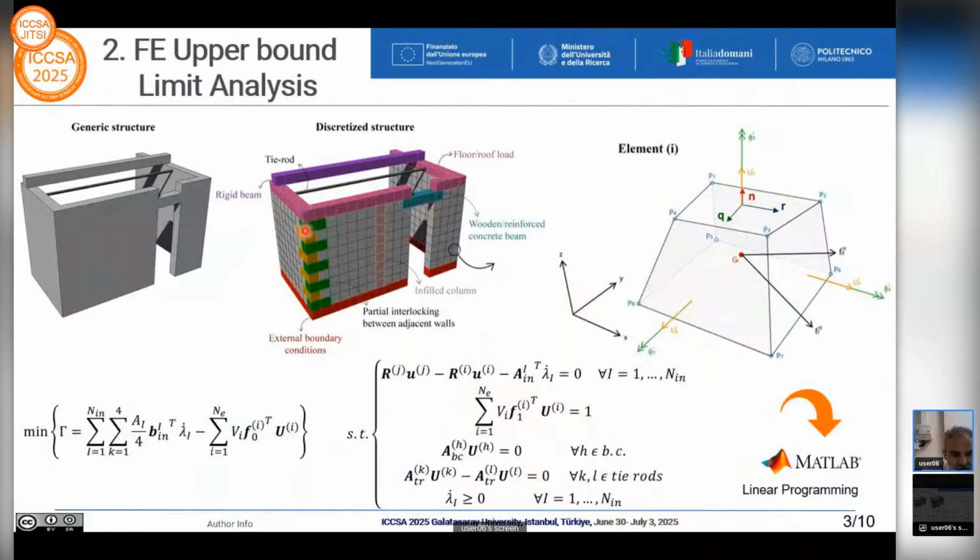We have the possibility then to model the masonry material with a heterogeneous approach, with different blocks with their three-dimensional geometry. This is particularly important, for instance, and it is well represented here, when you want to take into consideration the interaction in terms of strength between perpendicular walls, so the role played by the texture near the corner. And of course, you can also model masonry as a homogeneous material, and we will see in the next slide in which manner we deal with the